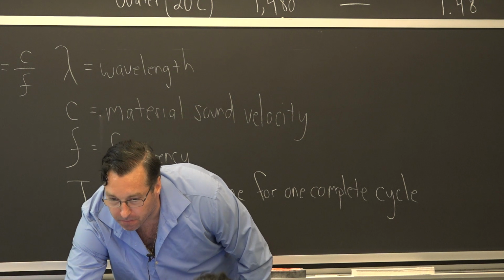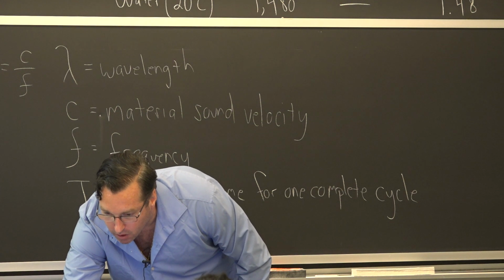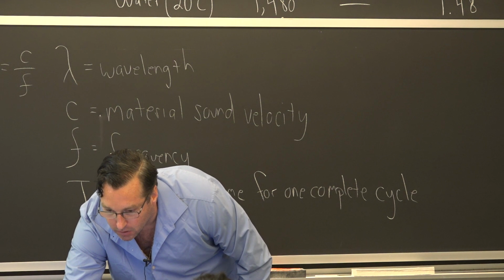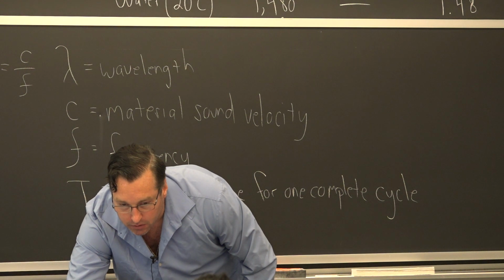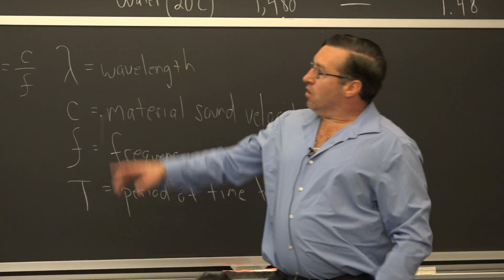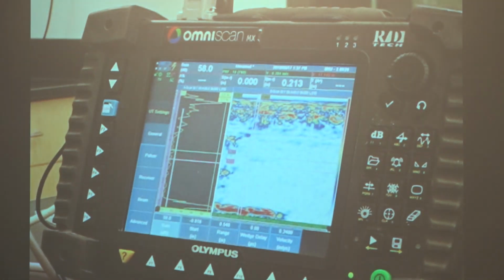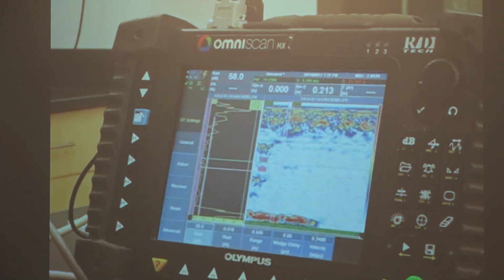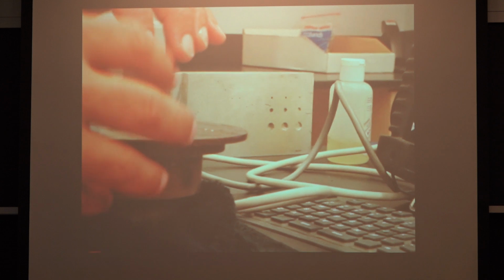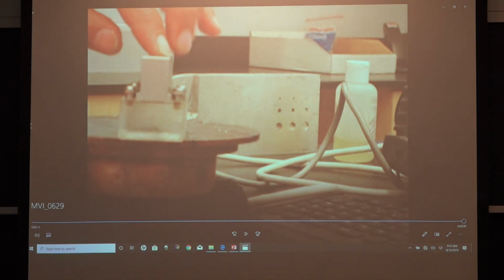So before we're finished, I do want to show a video of the inspection. What you're seeing on the left, that's where there's noise. There's noise occurring where that amplitude is jumping around just based on the noise in the electronics. So when you have the probe on the sample versus when you have the probe just in air, you can actually see some movement in the amplitude.